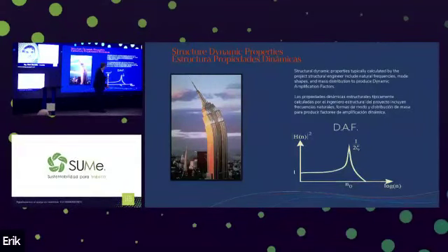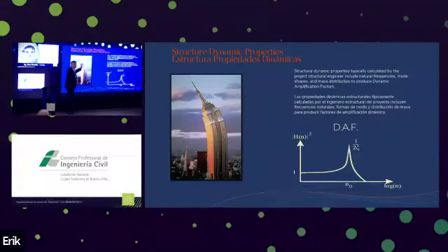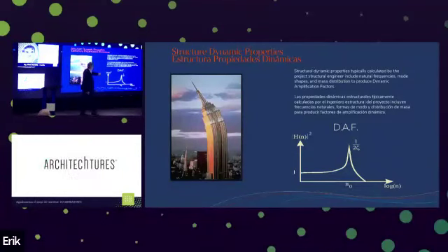What it does is it allows for us to account for the amplification of response of a tower at its natural frequency. And obviously, this is an exaggeration of the Empire State Building, but at a reduced amplitude, it does vibrate in this shape and with a natural frequency. And it'll have a heightened response to the natural frequency proportional to the damping of the structure.